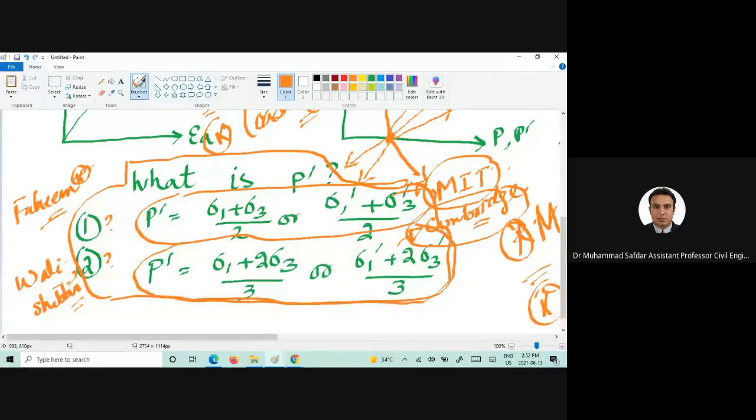But Cambridge University, as you all know, has the Cam-Clay constitutive models. So they have also done lots of work in critical state soil mechanics: Schofield and Wroth, Jeffrey Wood. So they call P prime the mean effective stress, and they used definition number 2, which Wali and Shabir were saying is the correct one.